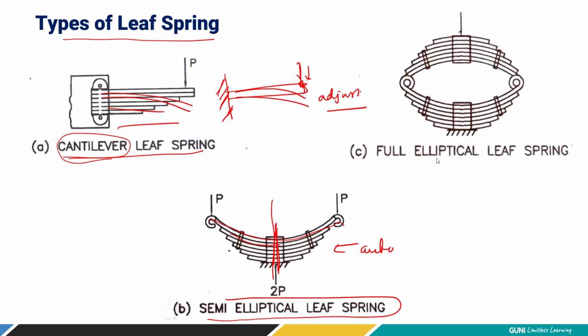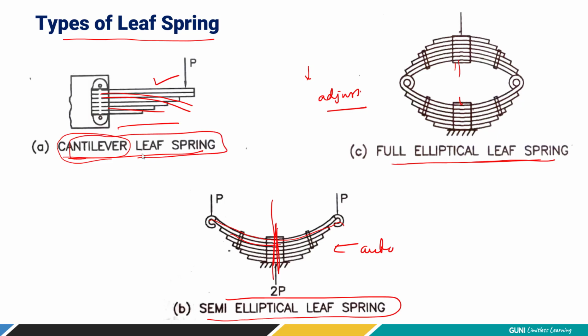When you have two complete full elliptical springs side by side or one over another, we refer to this as the full elliptical leaf spring. Now all three offer you advantages and disadvantages, right? If you have a very heavy load, then the cantilever beam leaf spring is widely preferred. But for general applications, semi-elliptical springs are widely used in automotive. Even for smithy work, if you have a mechanical press to absorb the shock, they also use this semi-elliptical spring in older machineries.